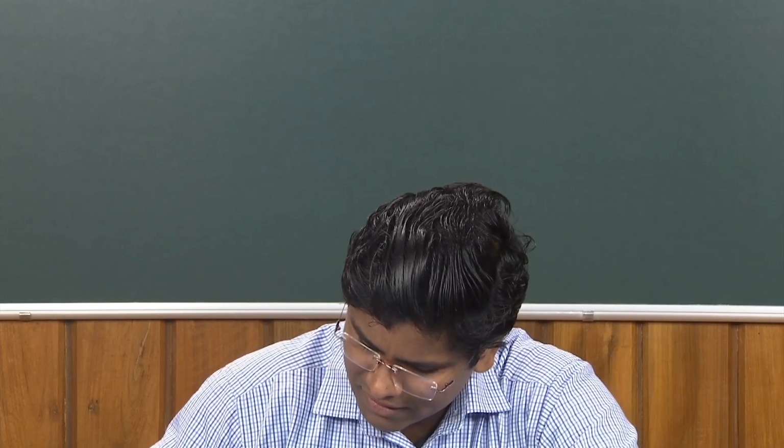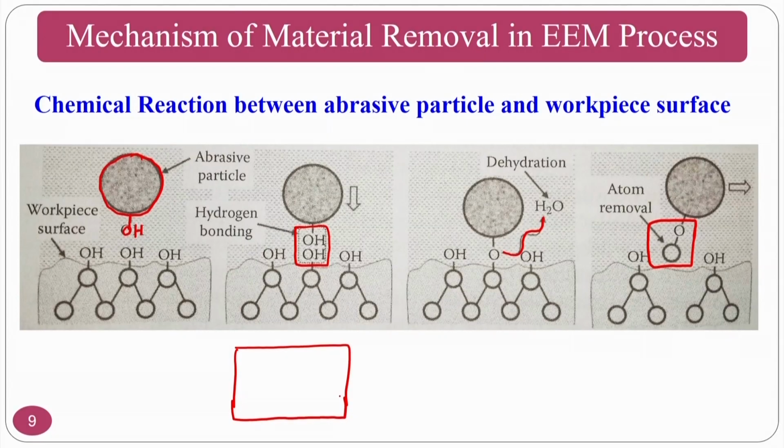If this is a surface in terms of grinding or diamond turning, your tool will go, come back, go, and come back again. So, this type of scratch marks will be there, even though you are going to get a surface roughness of about 20 Angstroms or something.